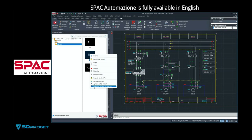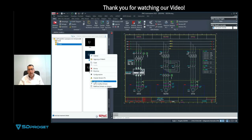It can also be useful through the open file path if I have to make a block very similar to that, but not the same. I open that file path, copy paste, and then go to open and edit symbol. So I open that environment with only the commands that serve, with the menu of the custom BLK suite, which is always very useful to use the right attributes, precisely because if the attribute tags are missing, then the program will fail the cross-reference or does not do the list, etc.